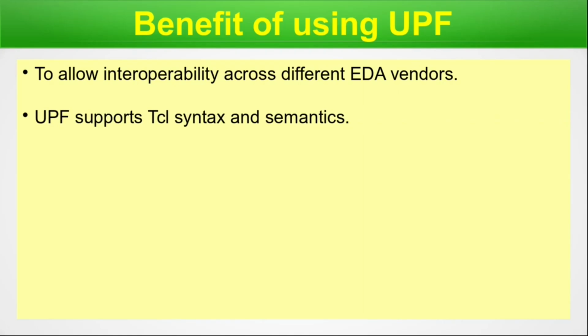UPF supports Tcl syntax and semantics. So it very much tallies with the Tcl syntax and semantics. There could be a lot of Tcl commands inside, and you can use Tcl wherever you want. UPF is constantly evolving. It's not a static language. It is constantly developed by Accellera and new versions are coming up.